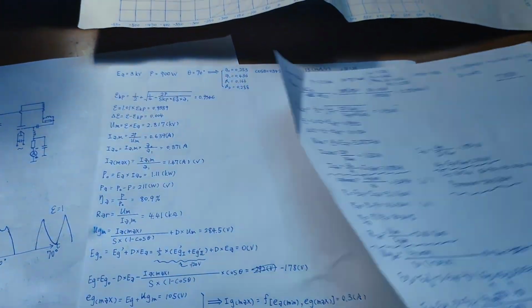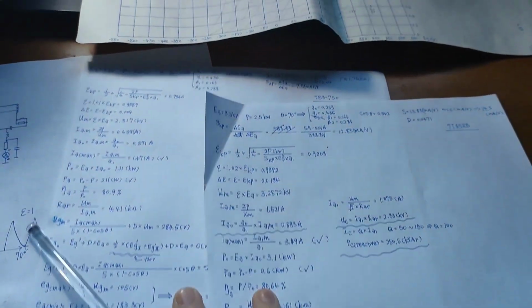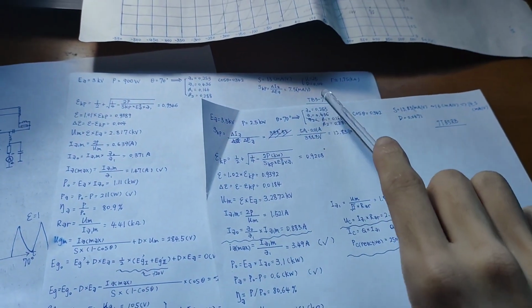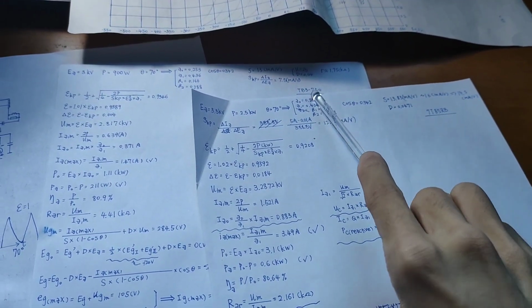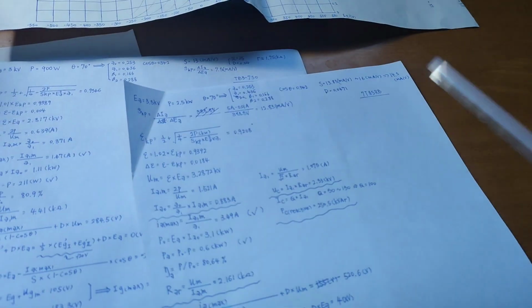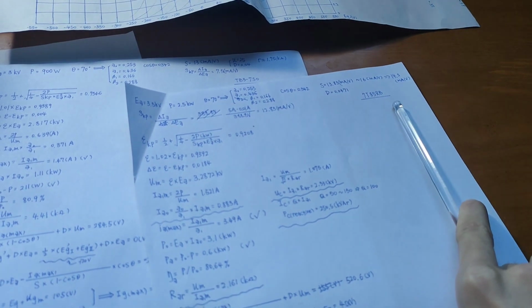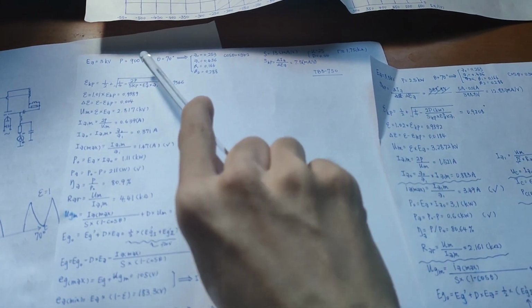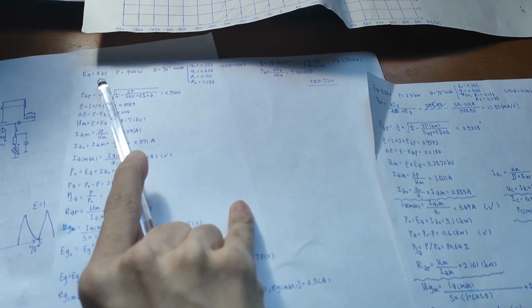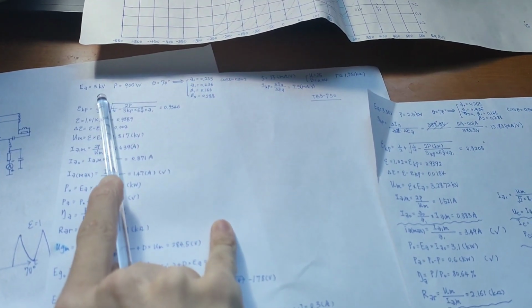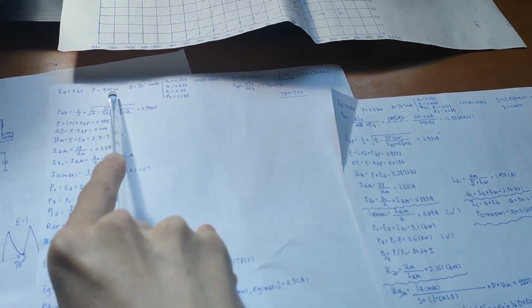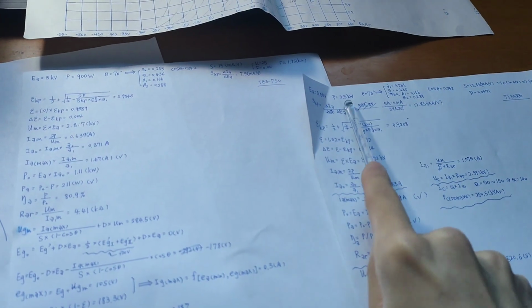Actually, I have calculated for several tubes, and I just picked out two calculations which I wrote very clearly. This one is for the TB3-750, and this is for the 7T85RB, which is made by Toshiba or Canon, an industrial triode used for RF heating. First you decide your anode voltage, which will be limited by your anode supply in most situations, like this one here. And you will also need to design your output power, your needed RF power.